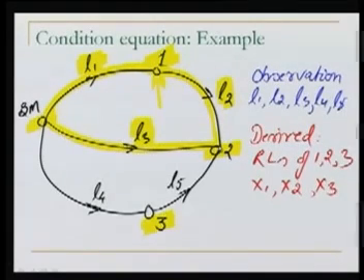So we have introduced redundancy in the observation. Further, in order to determine the RL of point 3, having known the RL of point 2, I am finding the difference in elevation between these 2 points, that is L5. So I can determine the RL of point 3 also. But I am also taking one more observation here, that is L4. So again there is redundancy.